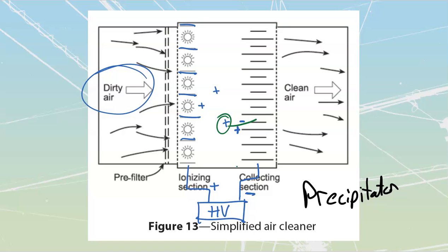But because we're working with high voltage, never assume you can wash anything that's going to be a high voltage component. Clean them off with compressed air, someplace that's going to be outside, obviously with the dust mask on or something like that. Do not ever open these, though, when they're operational. There's nothing to see. You cannot see the electricity. You're not going to be able to see the dust particles. It is going to be absolutely anticlimactic to open it, and it's going to be highly dangerous because we have got high voltage DC sections inside of here.